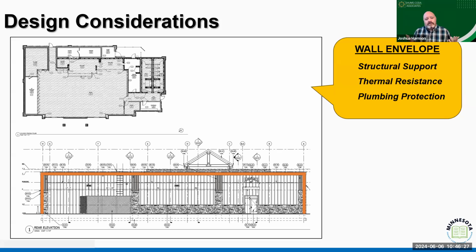That's usually a good one for me, because I think it's the one most often affected by changes in temperature. Electrical conduit, maybe not so much, and HVAC to a degree, but plumbing is one of those things. If it's not properly insulated, not properly located within the building's thermal envelope, it's going to be the most obviously affected when it comes to freeze-thaw. And you guys know that probably more than some of the warmer climates, right?